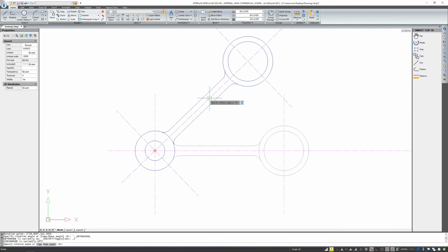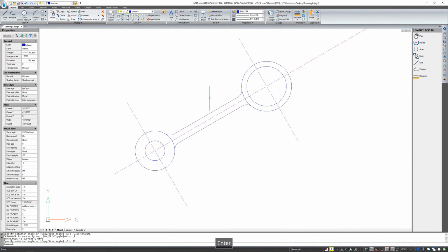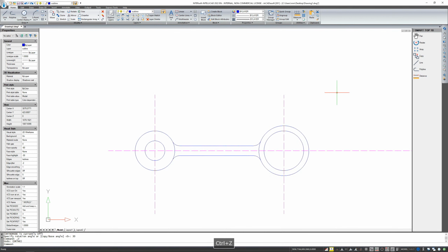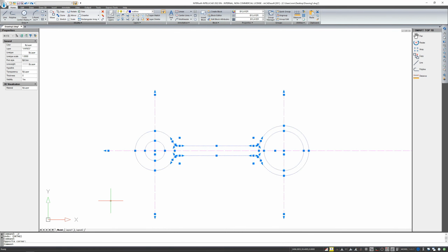And I would like this element here to be moved 30 degrees away. But I would also like this element that I marked to stay. The default is that when you rotate this element, that is the original element, as if you move it by some angle. If I now enter 30 and confirm with enter, this part of the drawing will rotate. I, on the other hand, would like this element to remain and, additionally, to have it reversed.